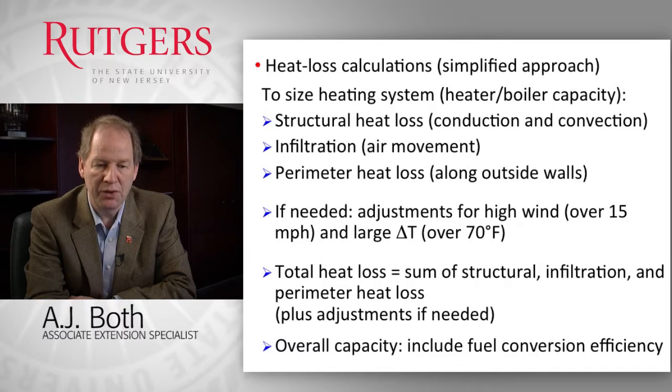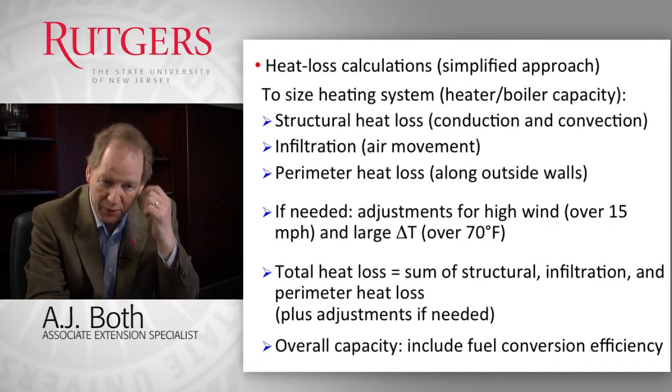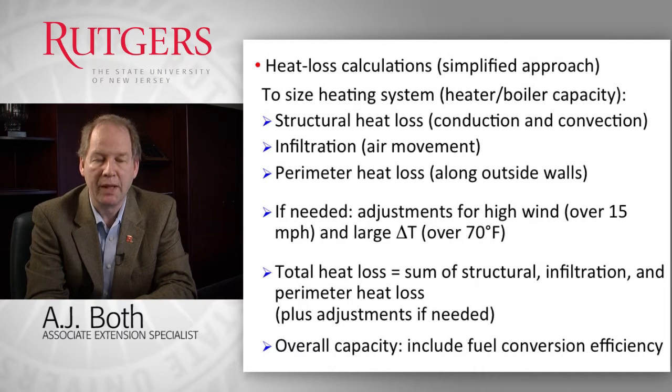And then we have heat loss around the perimeter where the greenhouse structure touches the floor, and especially when the floor is in connection with outside ground, and if that pathway is relatively moist, water is a very good conductor, then we can have significant heat loss around the perimeter. So if we know the amount of heat that's being lost through these three different processes, we can then calculate how much the heating system needs to make up in order to maintain the set point temperature.